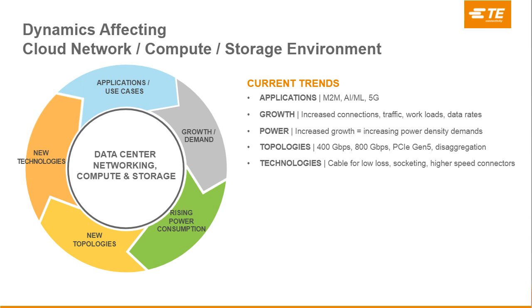If we want to talk about the design, it's actually a smaller footprint of gear. So it's about 30% less in size than a typical IEEE metal-clad gear. Most of this gear is going to be called gas insulated or prim set. And what that's going to do is it goes in line with what's inside the data center. The high density racks and the switch gears that go inside is just now migrating to the outside. And it assists the owners with less land acquisition with that. And we'll touch base on that in just a second.